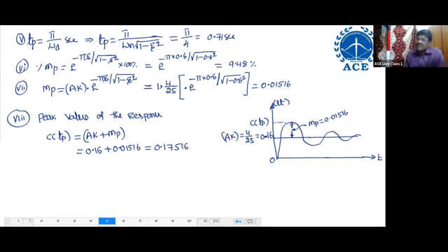If you have any doubt, check the percentage of peak overshoot, and you will get 9.48 only. How to check percentage of peak overshoot? The formula is c of t p minus c of infinity, divided by c of infinity, into 100%. c of t p is 0.17516 minus c of infinity 0.16, divided by 0.16, into 100%. You solve it, no doubt, 9.48% only. It never changes.